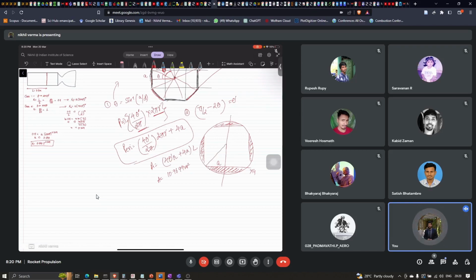Can you calculate the area within the chord? I'm just giving the idea how to calculate this. So you can calculate this area, then you have to multiply by the length and by the density of the propellant. So if this is the area, into 4, with this you can calculate what is not m dot, it is m. So what is the mass of the sliver? I hope it is clear, right?